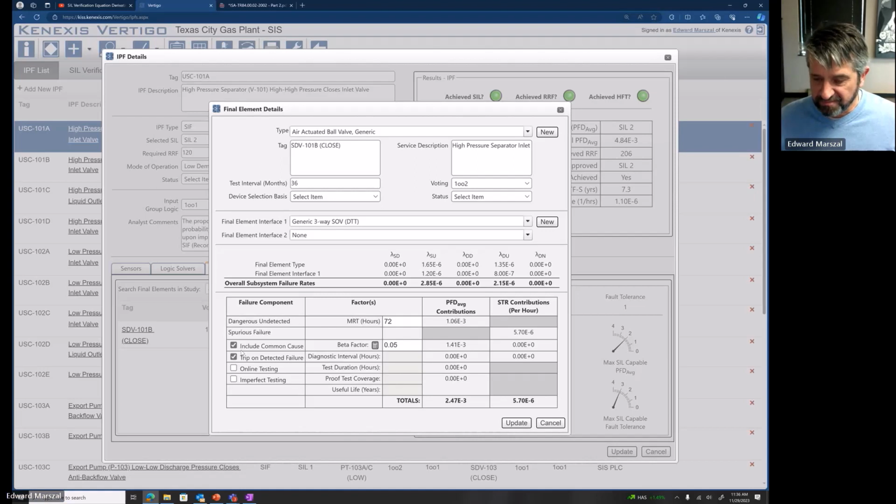But even though you're adding all the initiating events together to get a total frequency at which the accident event will occur, each one of those initiating events was independent of each other. So even though you're using the same IPL for initiating event 1 and initiating event 2, those initiating events are independent points in time.